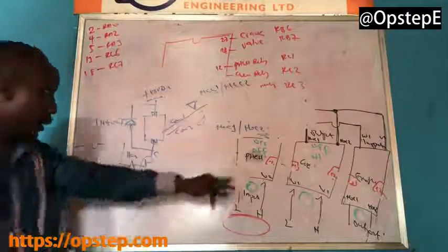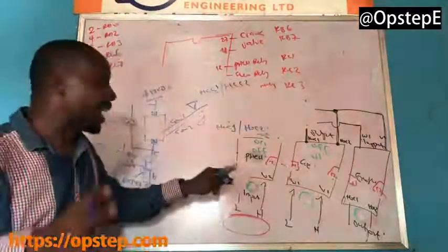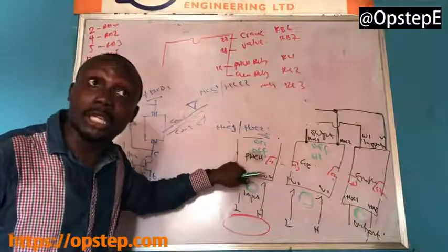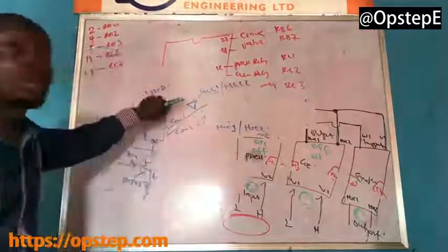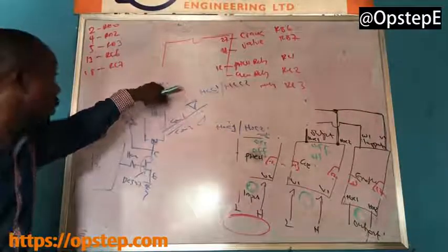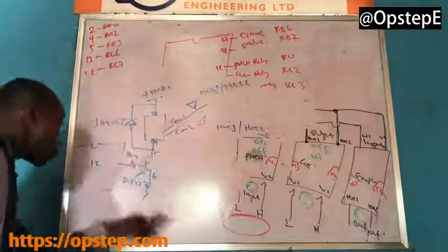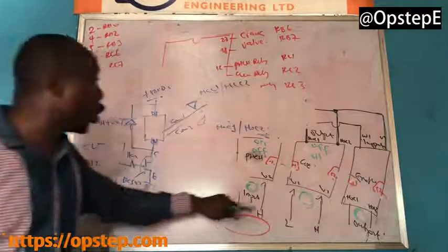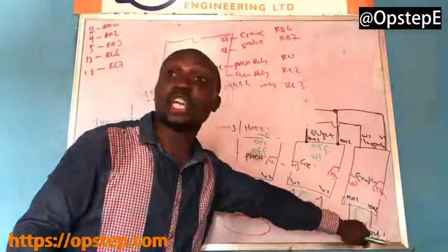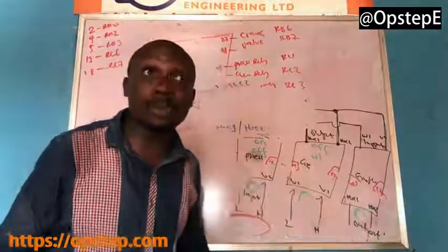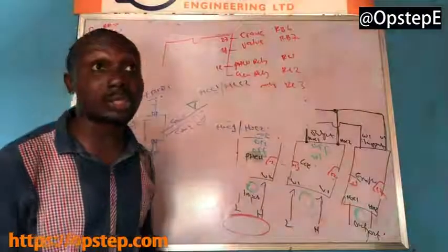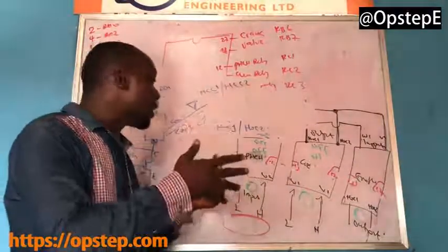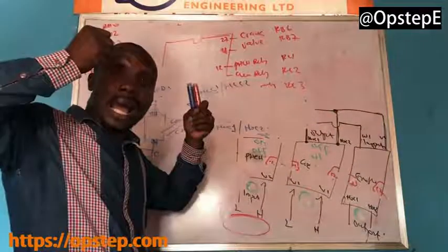Do you get it? That's how it's going. But understand that at every point in time, one of the relay's coils is already connected to what? To positive. It's just waiting for the negative through this transistor. Do you get the point now? Just the way your load too is already connected, just expecting the second one to switch it. Except that this time, in the course of the system, the live and neutral are withdrawn.